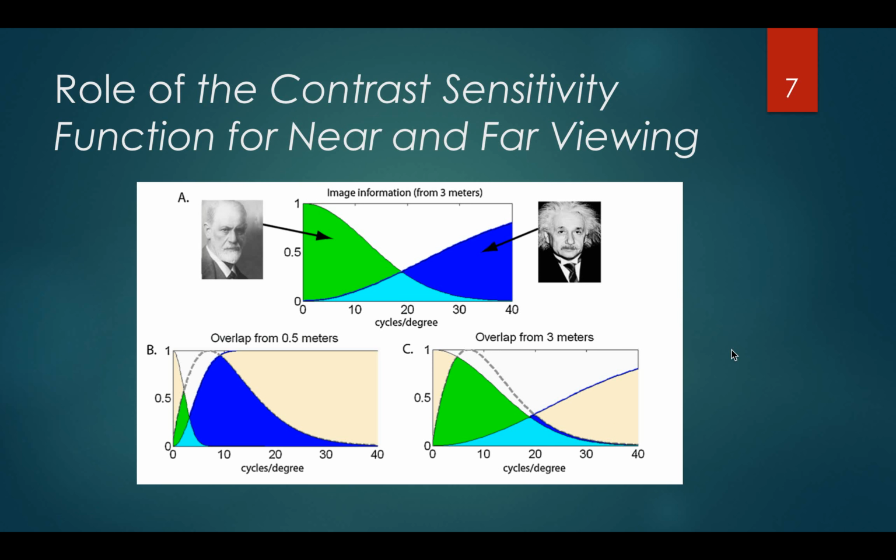It's well known that the human visual system sees the world through the contrast sensitivity function, which acts as a bandpass filter, effectively making low contrast information at particular spatial frequencies invisible to the naked eye. So, when we're producing hybrid images, we will have to consider the bandpass frequency of the filter in order to produce the best image.